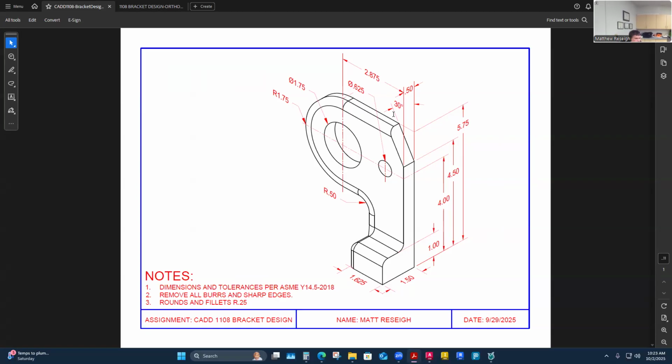So I'm going to come back here and notice that 625 is critical. I don't want this to round to 63. That would be wrong, and so I don't want to hold less accuracy. I'm going to move this to 3 decimal places. I'm going to look at anywhere else that's going on. Everything else I see is 2, except for up here, this whole size is to 3 decimal places, and the whole location for the big hole is to 3 decimal places.